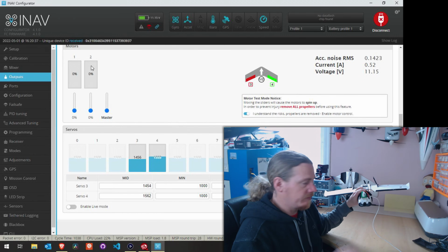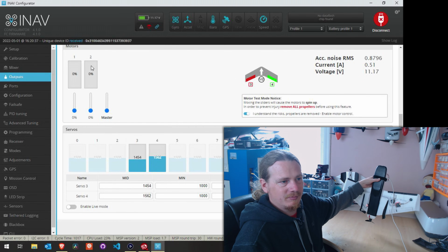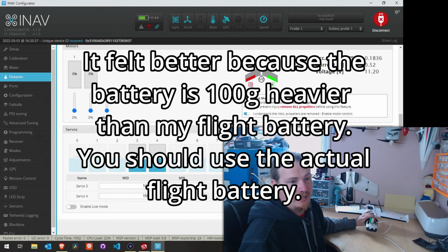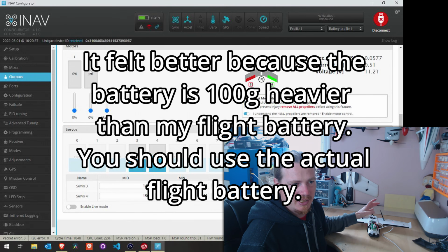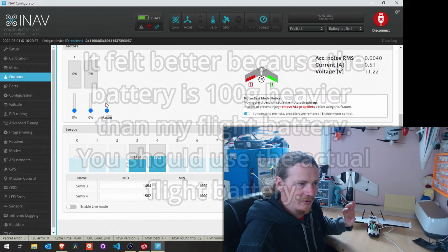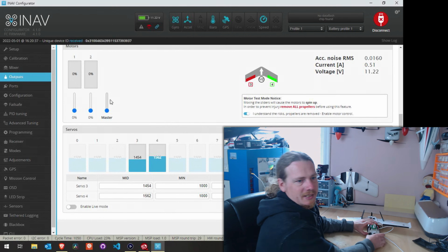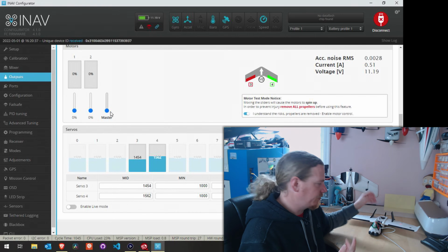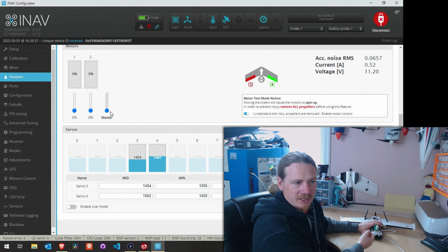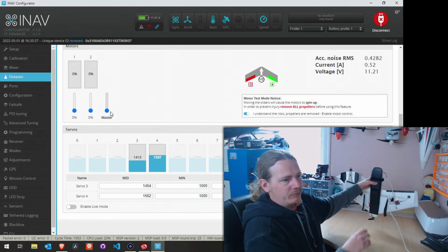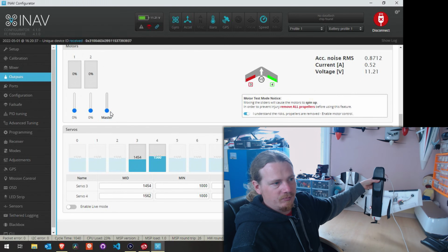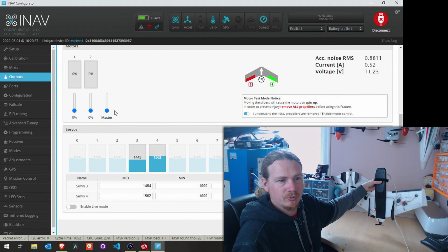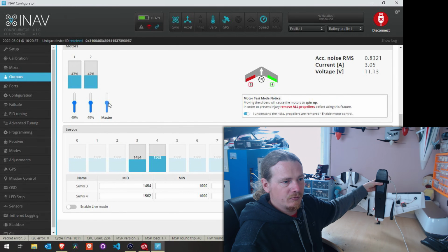Right, so you could see that I was trying to feel where it was by trying to unweight my arm, and to me it actually felt better at 98%, but I did lower it down because the launch throttle on this is actually set to 90%. So that's what you want to feel for. You want it to feel like it's weightless. It's not actually pushing towards you, but at the moment you can feel, even a plane this size, it's heavy, it's trying to pull towards the desk. But as the throttle increases,